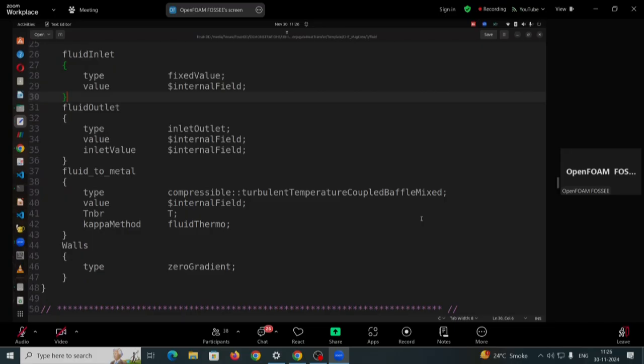At the interface between a solid and the convection, say if you have conduction and convection, then you will write minus k dT by dx is equal to h into delta T. That sort of a boundary condition. So what you're doing is you're maintaining continuity of the flux. So that is maintained as well as the temperature is maintained over here.